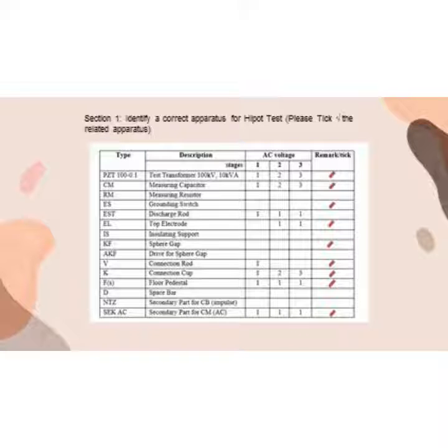The measuring capacitor measures the rate of voltage rise when the capacitor is charged. The capacitance meter measures the rate at which the voltage rises in that capacitor due to that current. The capacitance is then measured as a function of that voltage rise.